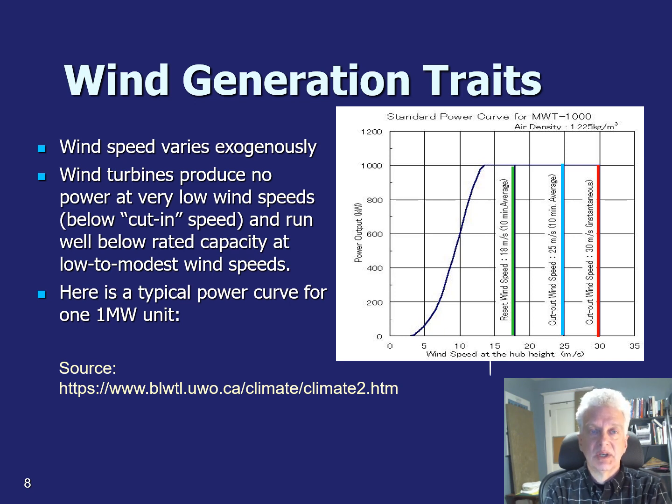As the wind increases, you can see there's a nice exponential increase in the torque and the power you can produce. And then as you approach and pass 10 meters per second, that S-curve begins to level off at the rated capacity of the turbine. So you have more torque after about 12 meters per second than the system can extract, and you're just limited by the capacity of the generator unit inside it. And then from 13 meters per second on up, the unit tops out. No matter how much more the wind blows, it doesn't get any more powerful. It's just producing its rated capacity.